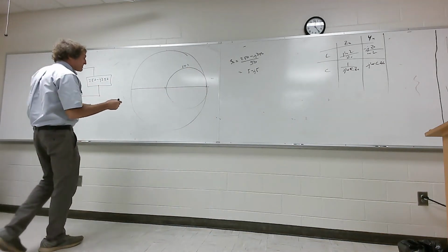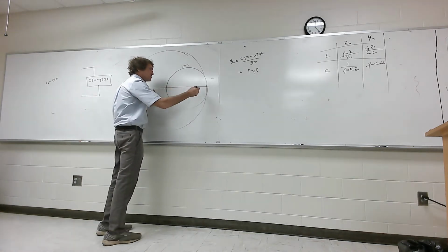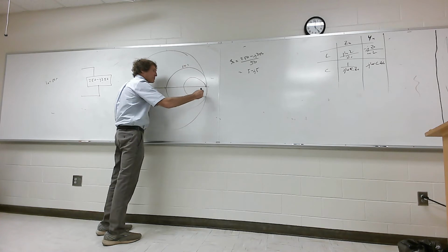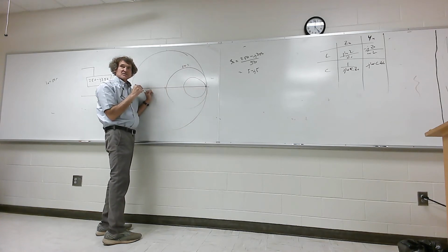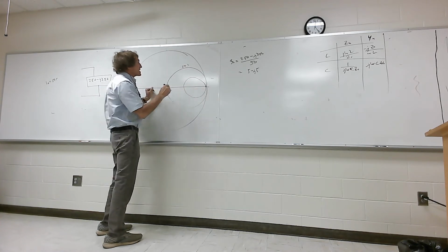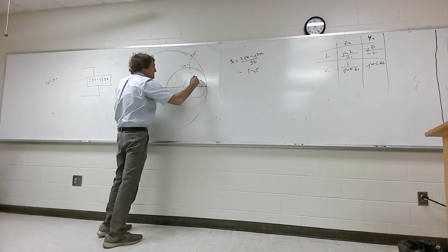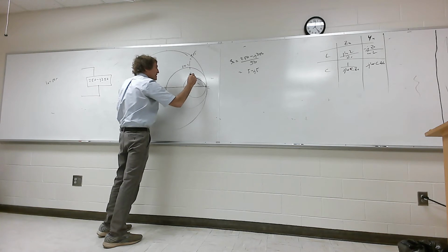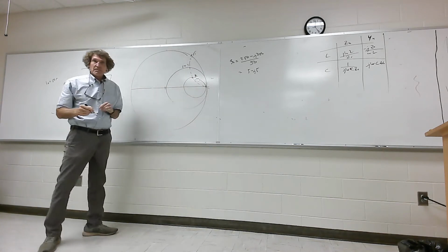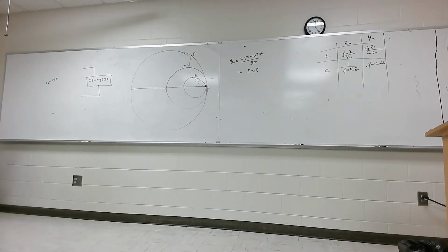And this is an estimate. If that's 1, let's see, 2, 3, 5 is probably right about there, but I might be a little big. The real value is 5. For j5, it's somewhere over here, if you look on your Smith chart. So it's somewhere about here. That would be my normalized ZL. Can y'all follow me? Got that? That's inside the 1 circle. We all agree. The only thing we can do now is we've got to go to the admittance domain.